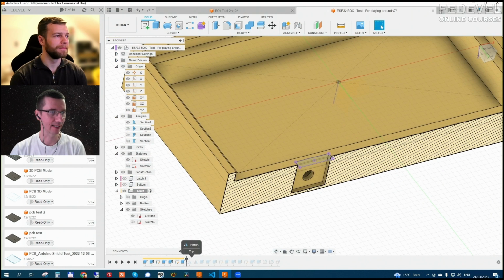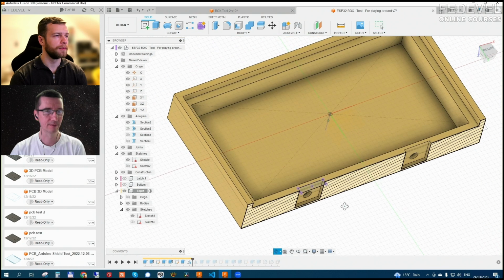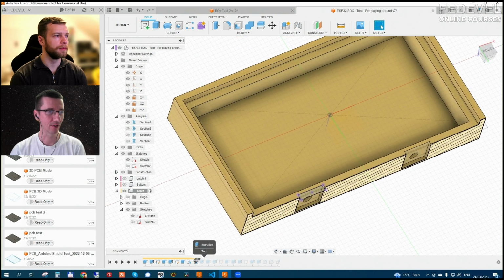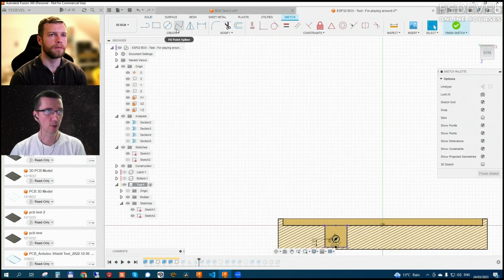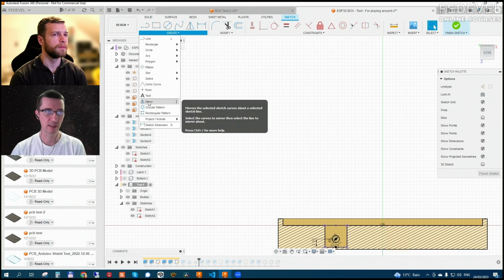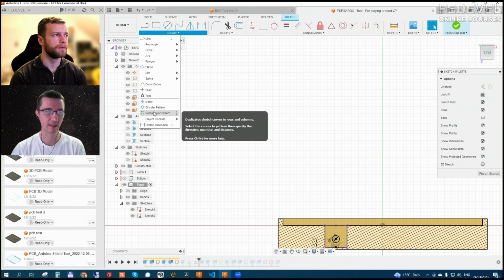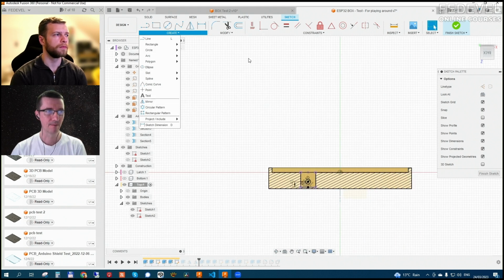Now it's simple again, mirror feature and then mirrored again. So again, I only created this once and mirrored this. Theoretically, you can use mirror features also in Sketch. If you go here, you can see here is mirror, pattern, and everything. But as I said before, in Sketch, you don't have a timeline, so you can't go back and change the parameters.